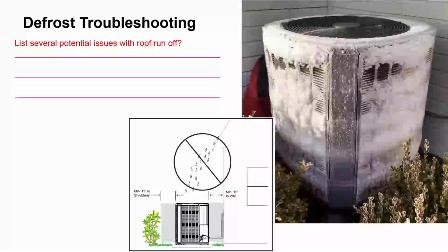Well, that's because the water would freeze onto here, it'd start up, and ice would fall onto the fan blade. All we did is we moved this unit about 10 feet to the north, and all of our problems went away. So make sure you're watching for those types of issues.